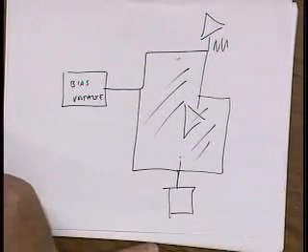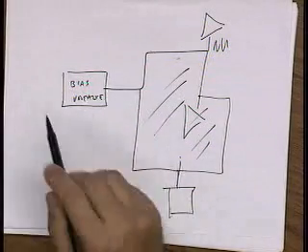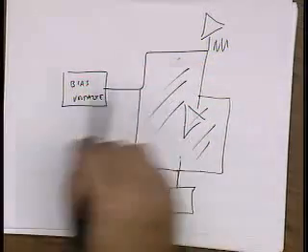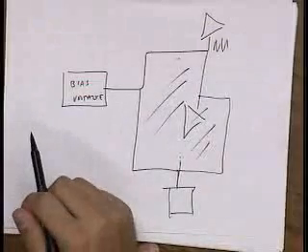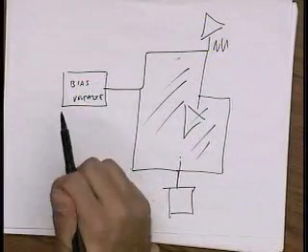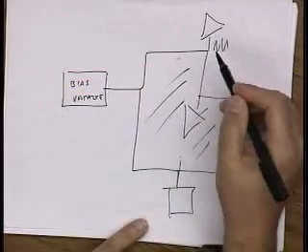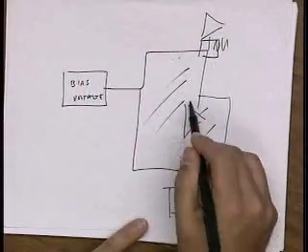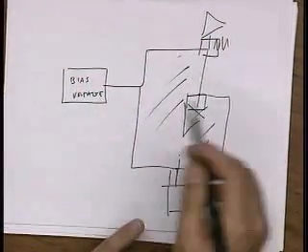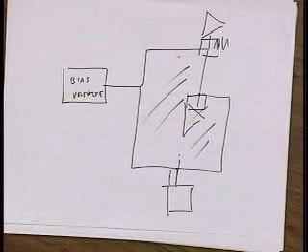And so basically, even though it's a nice idea to have one master bias voltage and just route wires everywhere, it saves power and area, a lot of times it's actually a safer bet to put things close by, especially if the power penalty is not too large.